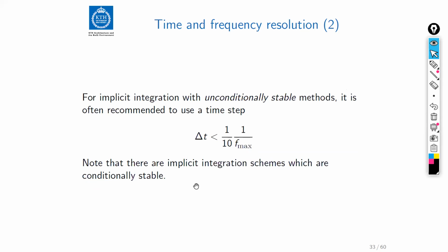It should also be noted that there are implicit integration schemes which are only conditionally stable. So if you choose a too large time step in those implicit schemes, you will have exploding solutions anyway. These are rarely implemented though in commercial finite element programs. So I think it's safe to say that in the commercial codes, you will only be subjected to these unconditionally stable methods. And if you dare go outside this box and do stuff on your own, of course you are obviously reading and learning how to do that. So then you will have to figure out those details for yourself.